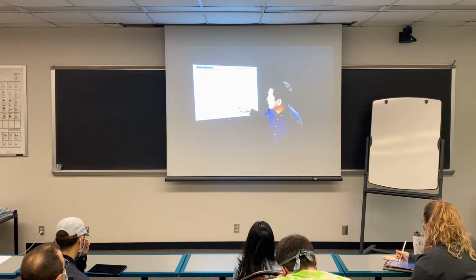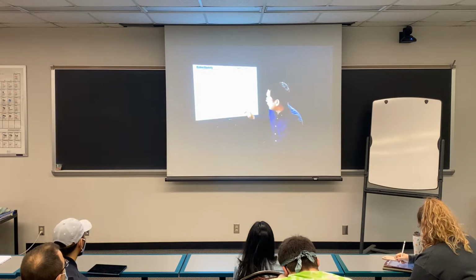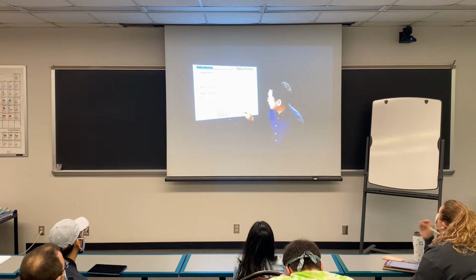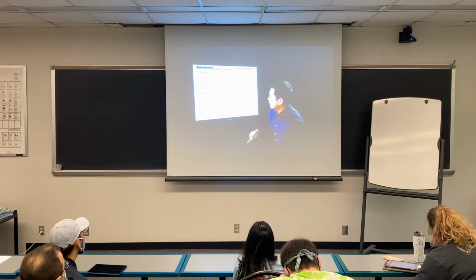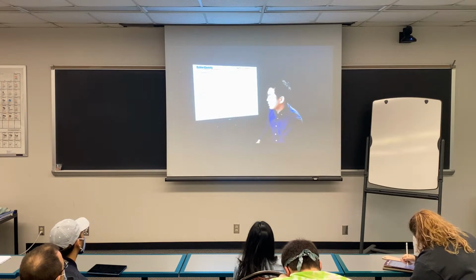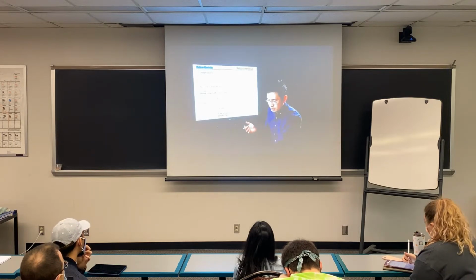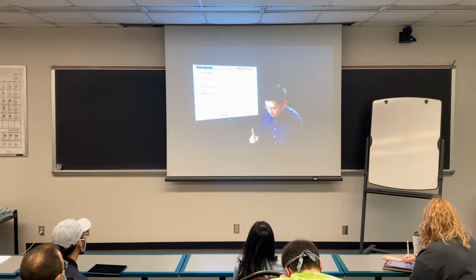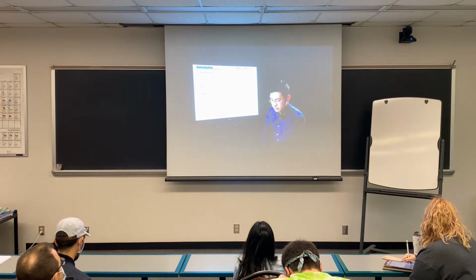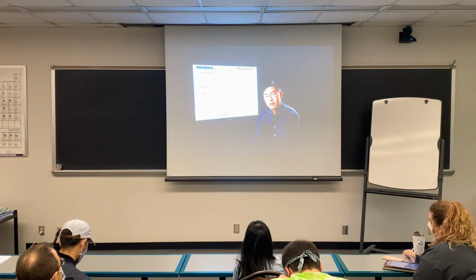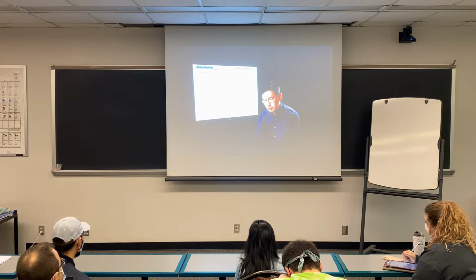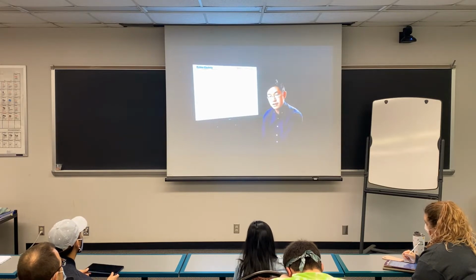This needs to be considered by modifying the model with another parameter called Me, where we consider the modified entanglement density in addition to Mx, the original term. This is the additional fitting parameter, and it allows one to capture the crosslink density within the network better.